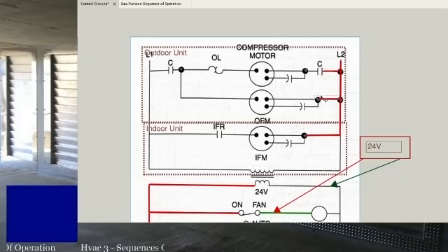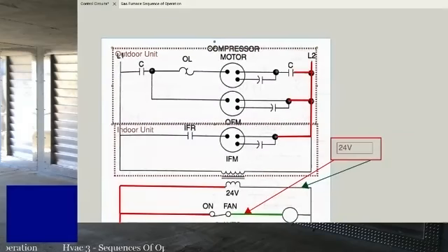As a matter of fact, no. The compressor, the way they've got this drawn, actually, the compressor on the contactor on the outdoor, both legs of power are cut off by these two switches right here. Make sure you guys can see what I'm trying to point at. Yeah. So on the compressor, both legs of power are cut by the contactor.